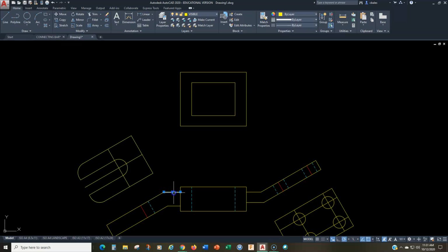And we can also take care of this section and this section right here, projected up here, because again, these are parallel to the plane of projection. So that is an offset of 6 from here to here. And I'll just project this up here, and we'll extend that there, and then the width on here is 50, so we'll offset that, and we can trim that out like so,